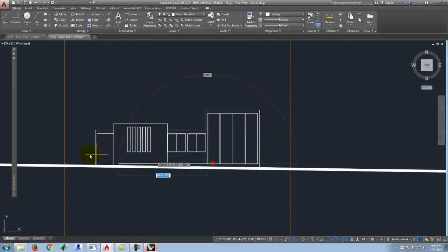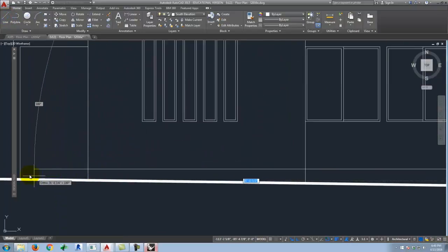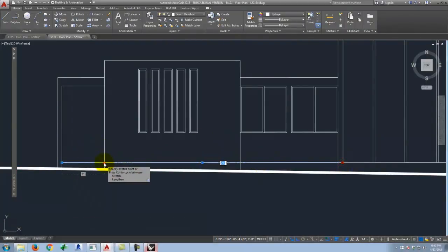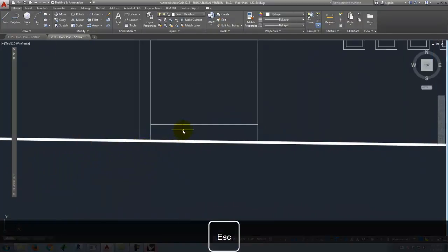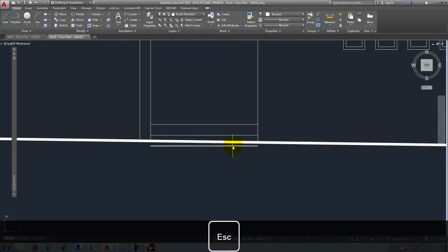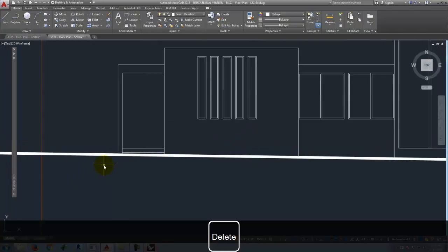It's going to be at floor level, so we'll pull the floor level line across like that. And then let me take this end and pull it over to right there. This has a couple stairs, so I'll offset this by maybe 6 inches going down. And that one's covered up, so we'll go ahead and delete that one like that.